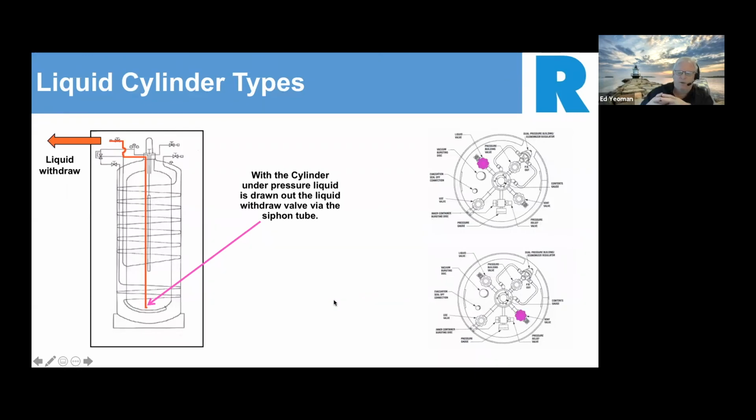The bottom figure is showing you the vent, which we didn't really talk about, don't have a schematic for it, but the vent valve obviously will regulate the pressure inside the cylinder. If a cylinder pressure is too high for you, you can always open up the vent in a safe location, where it's not blowing in somebody's face, and vent the cylinder down.